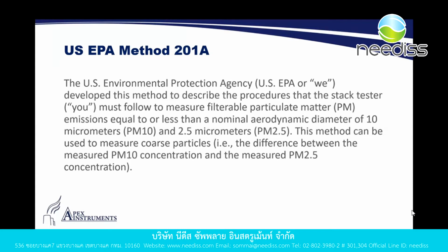The US EPA developed this method to describe the procedures that you, as the stack tester, would follow to measure filterable particulate matter, so the dust in the stack, equal to or less than a nominal aerodynamic diameter of either 10 microns, 2.5 microns, or the values of sizes in between 10 and 2.5.